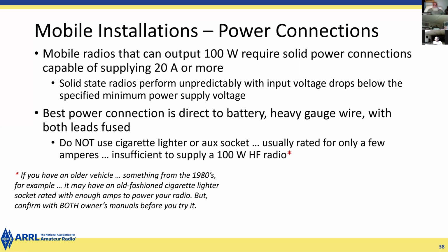1 or 2 milliamps may not sound like very much, but over a large amount of time, it can deplete the charge on your battery. So that's another thing that you have to watch out for that's not on the test, but is very practical to consider. As a matter of fact, any accessory you add to your car, when the ignition is off, you have to have a way to make it draw either no current at all or extremely tiny amounts of current.